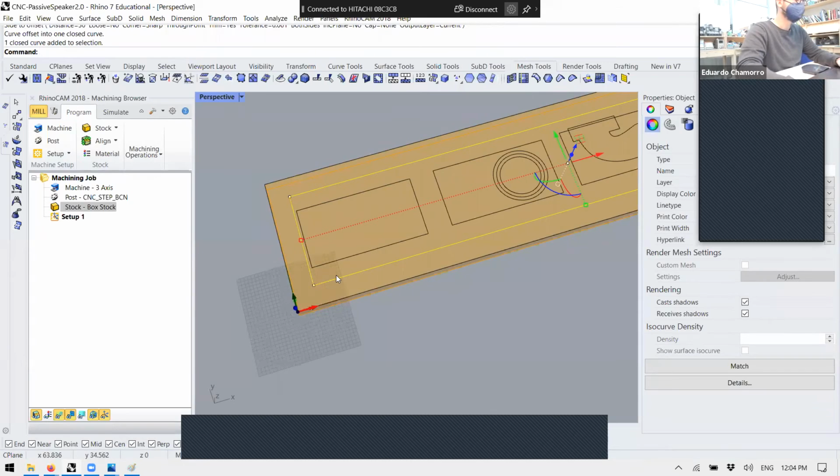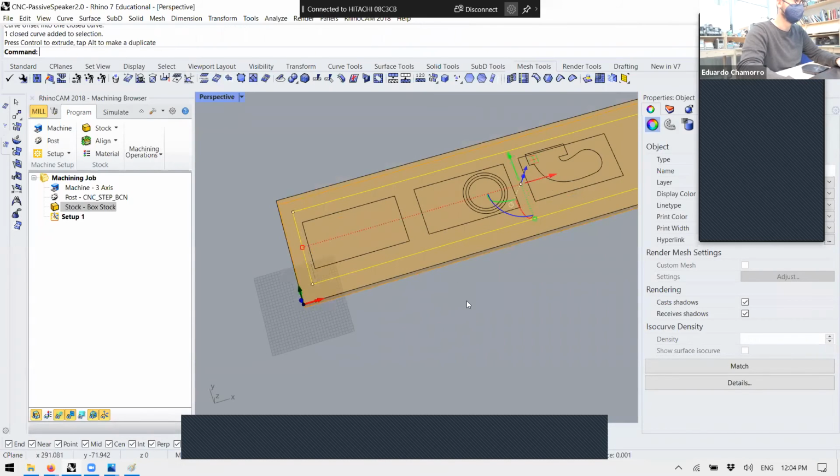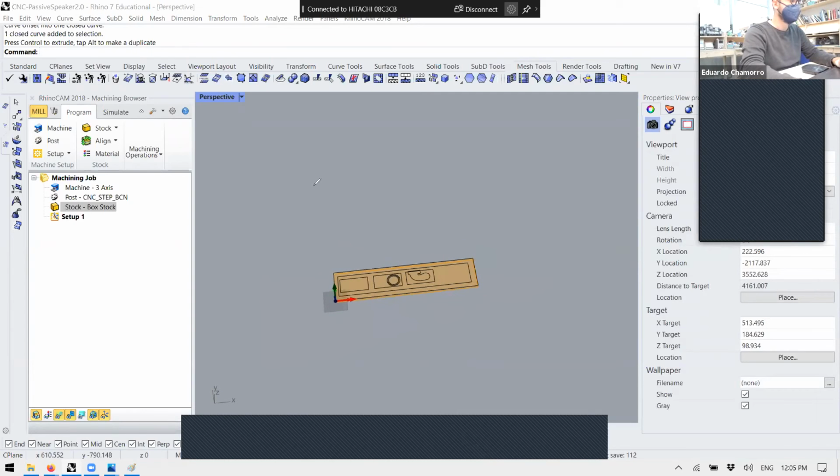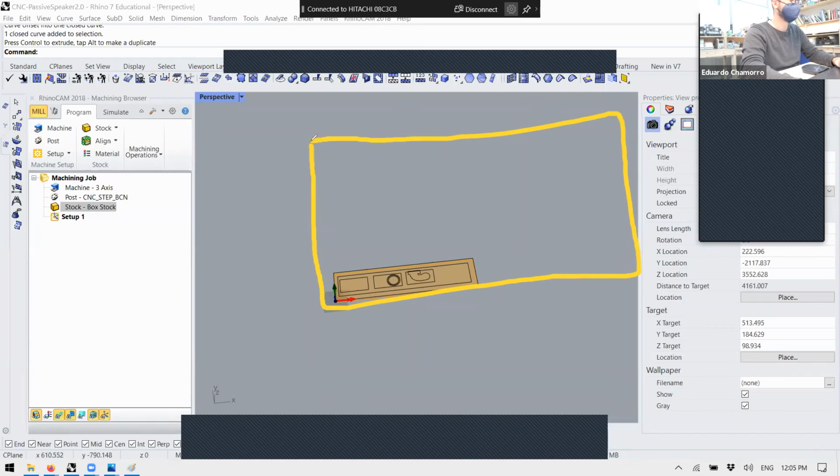Even so, I'm going to show you a little trick. For example, let's say we want to put a screw here. How do we do that? We're going to make the end mill go and touch 1 millimeter without the material attached. When you have big boards, for example, you are cutting a huge board, you want to have screws on the 4 corners. Ideally also like this, because this is 1.2. You want screws each 1.2 meters. So 1.2, 1.2, 1.2, X and Y.